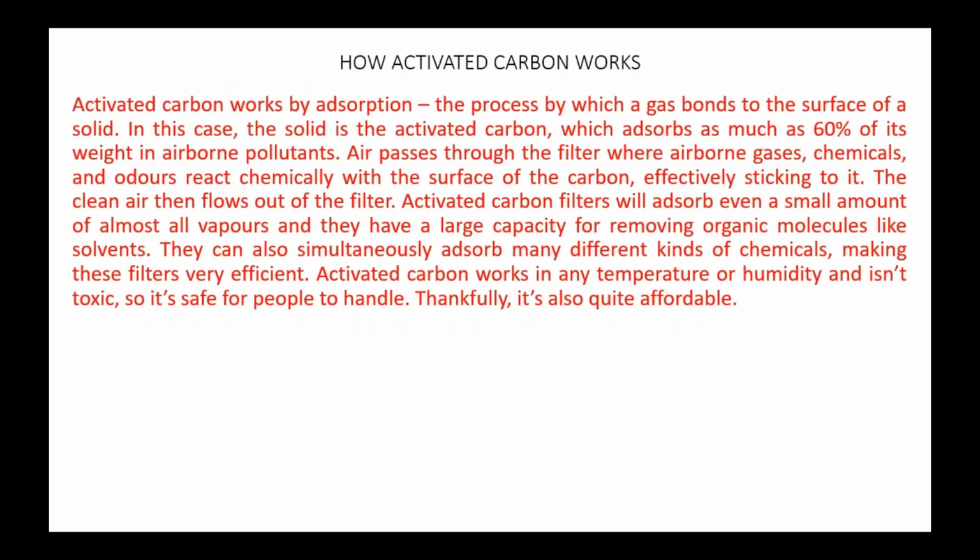How this activated carbon works is very important, because it works by the principle of adsorption. The process of adsorption is the process in which a gas bonds to the surface of a solid. In this case, the solid is activated carbon, which adsorbs as much as 60% of its weight in airborne pollutants. So the air passes through the filter, whereas the airborne gases, chemicals, and odors react chemically with the surface of the carbon and get stuck onto it, and do not pass through that particular carbon fabric layer. So this clean air then flows out of the fiber.